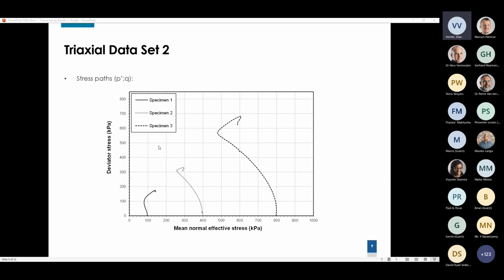Do you believe that it can be, especially in an undrained condition where volume stays constant and your void ratio is constant, that you've gone to a dilation stage and that the sample or soil at that specific effective stress is struggling and trying to move between the states of dilation and contraction, playing with the critical state? Would that be something that could occur?